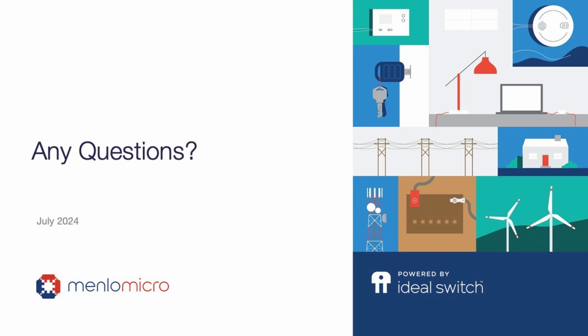And then going back to your first question, does a switch replace or work in conjunction with a SAW or BAW filter? So a switch can work in conjunction with the filter to choose different filters inside the system through software or any other kind of control. And so a switch will allow using a filter that filters one frequency at one point and then selecting another.